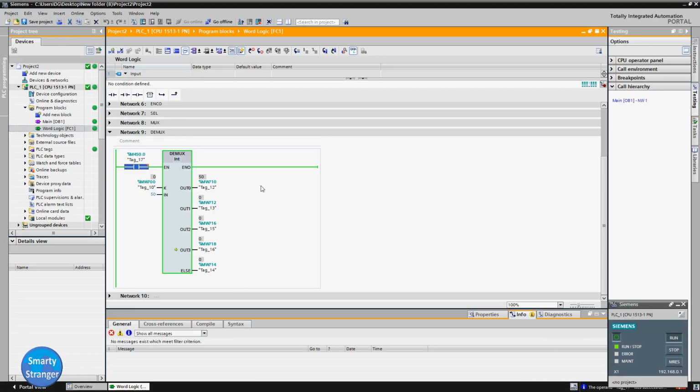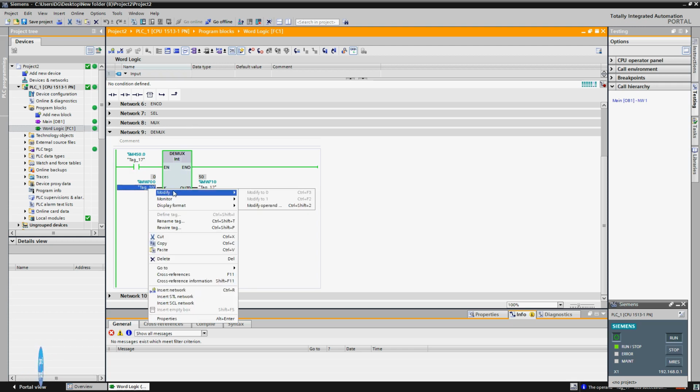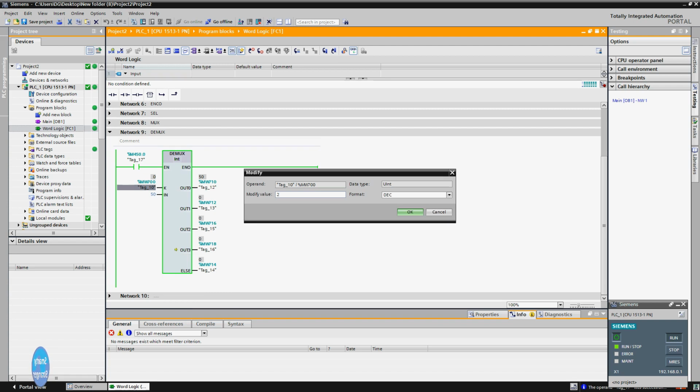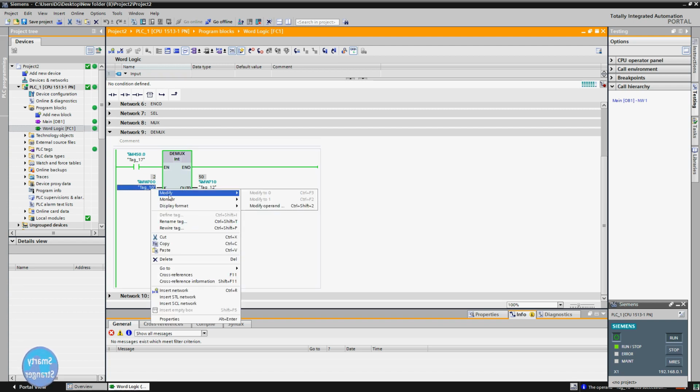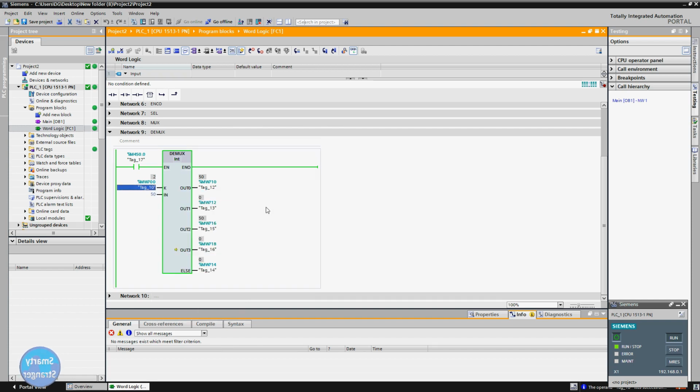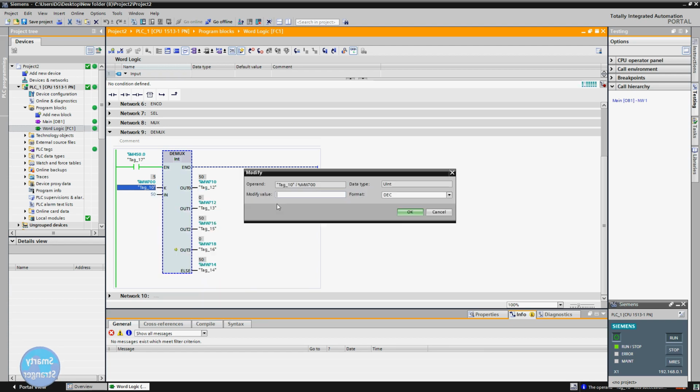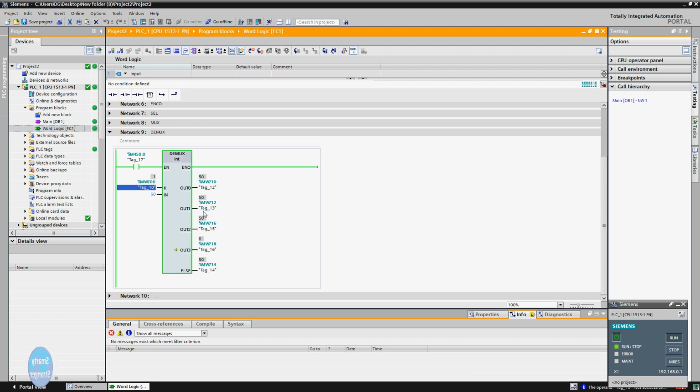First enable the instruction. Initially, value at K pin is 0. Instruction is forwarding the value of input to the out 0 pin. When we apply 2 at K pin, instruction forwards the value of input to the output pin 2. When we apply 5 at K pin, instruction forwards the value of input to the output pin 5. When we apply 1 at K pin, instruction forwards the value of input to the output pin 1.